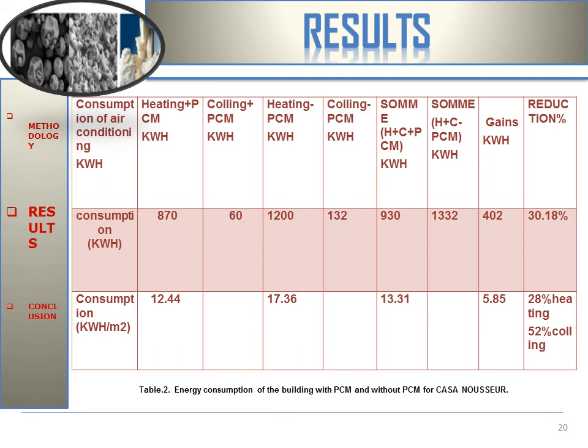The annual needs for heating and cooling are set by the Réglementation thermique marocaine according to the climate zone, and climate zone 1 includes Casablanca, Nador and Agadir. These annual needs are set at 25 kWh per square meter per year for residential building by the Réglementation thermique marocaine.